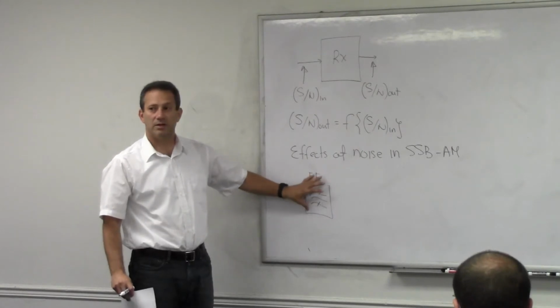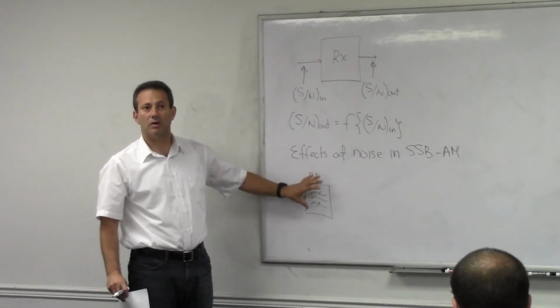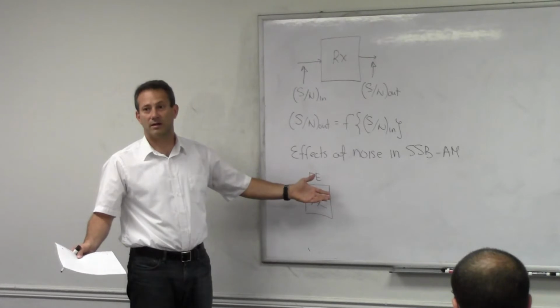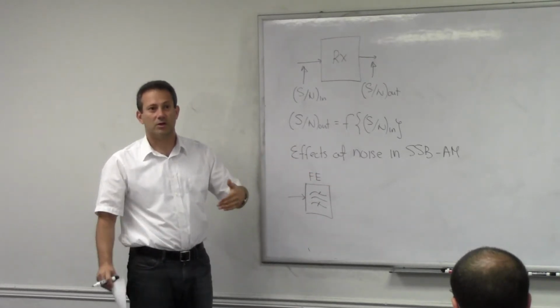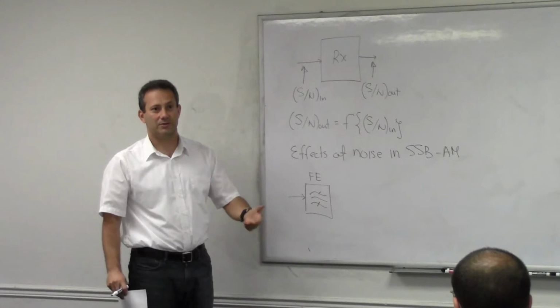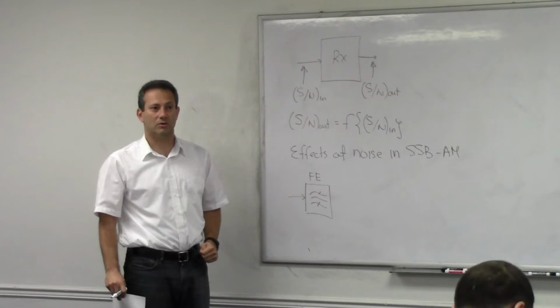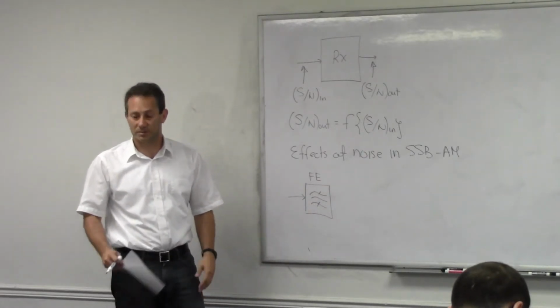Right? This limits the amount of noise that enters the receiver and only lets the noise that is co-spectrum with your signal. There you're kind of out of luck, right? Because if you try to filter that noise, you're going to be filtering your signal as well. So you cannot do that, right? So you have to let the bandwidth that's allocated to your signal go through, and along with your signal, there will be some noise that comes in.